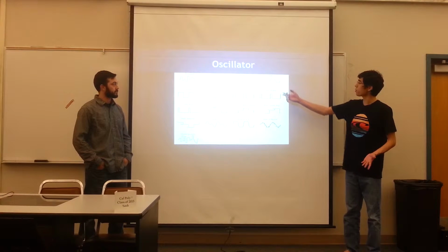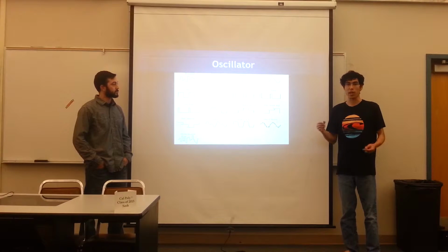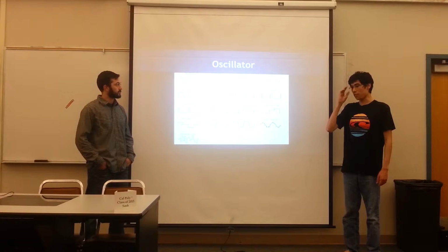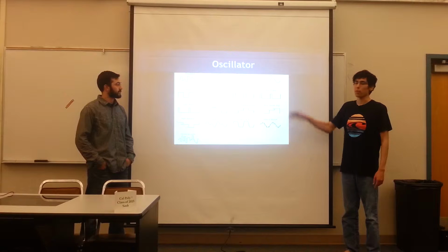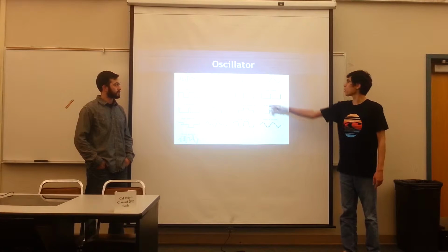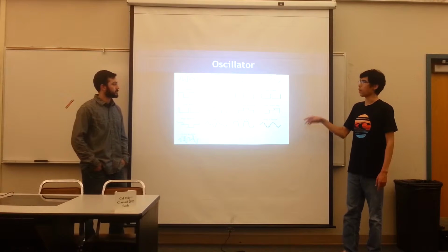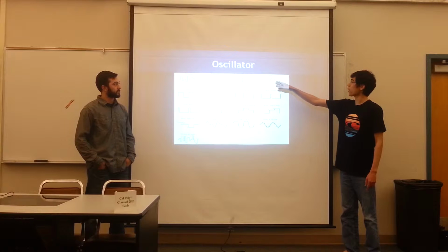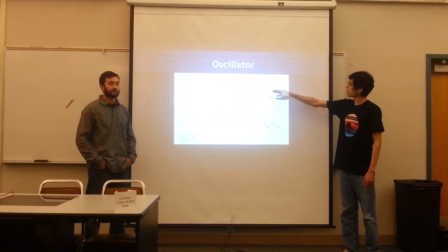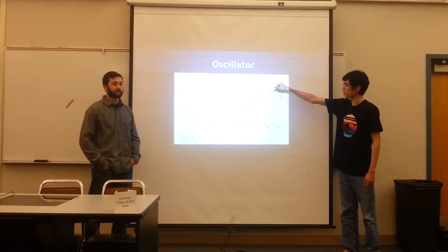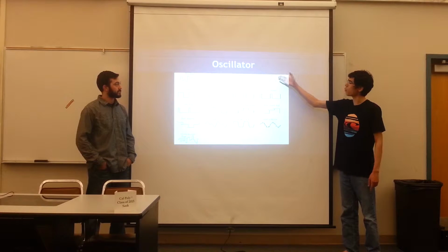So in order to get, for example, the discrete voltage levels of the sine, we resorted to using a PWM system in which a pulse modulated waveform is passed through a high-pass filter, low-pass filter, which cuts out the abrupt squares of our PWM input here and translates it into an overall DC offset. Now this alone is not enough to create a time-varying signal. In order to also get the variation over time, we have an additional timing circuit, which changes the PWM duty cycle over time in order to create different voltage levels. This, combined with the PWM filter, allows us to achieve different waveforms.